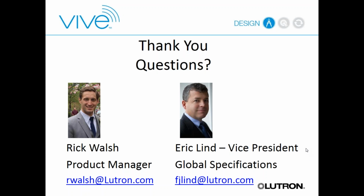Some other questions about high bay sensors came in, from a couple of people. We do have the ability to have high bay sensors communicate. We can use a sensor that has a module that communicates with our Clear Connect using a high bay sensor. In addition, one of the benefits we've really found with those types of applications is those wireless sensors can be placed down where the people are and not have to be limited to where the fixtures are. So again, this is one of those flexibilities of wireless that changes how you think about things: because you can place them down in the space and not have to have it tied to where the wiring is or where the control module is, you actually get more flexibility with those wireless sensors as you go.